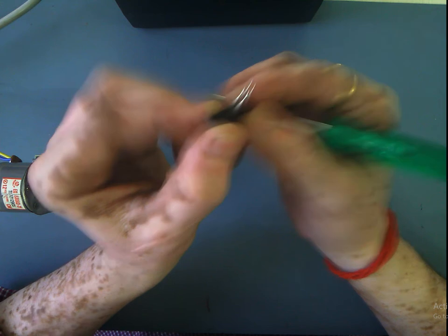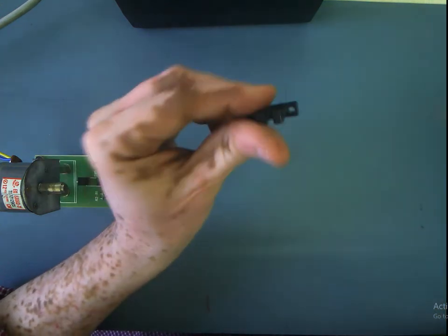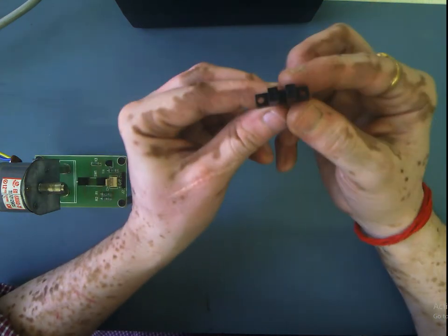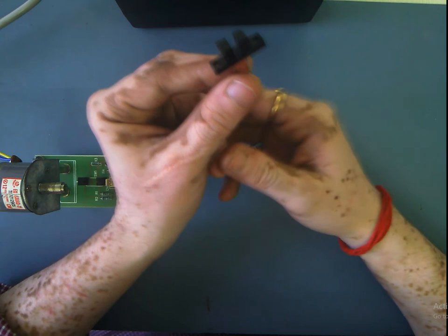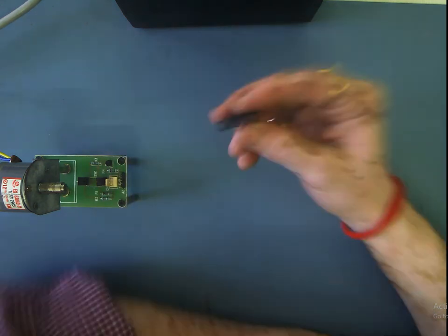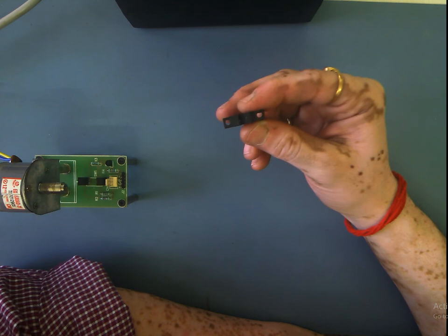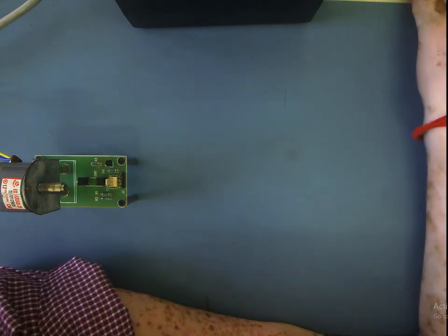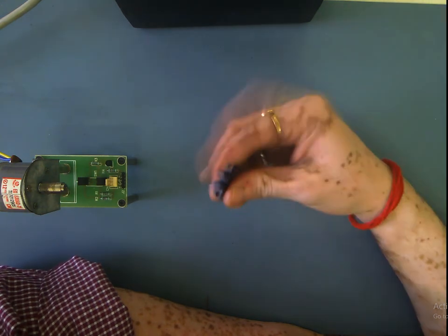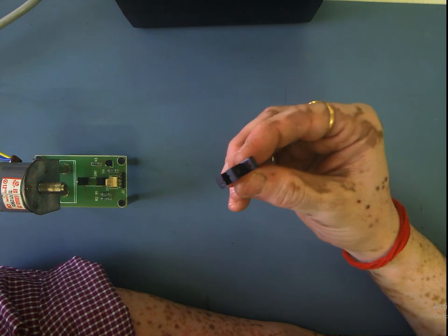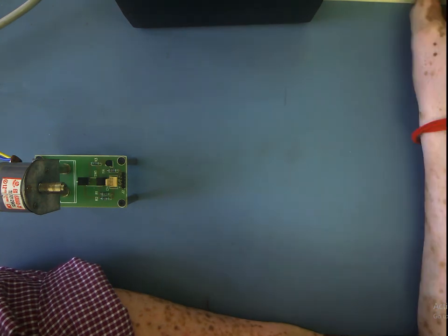As usual, when you connect it to any supply, you have to use a resistance in series with the diode circuit. Otherwise, the diode may get damaged by excessive current. Normally, we apply a 12 volt supply while developing a circuit with this slotted optical switch.